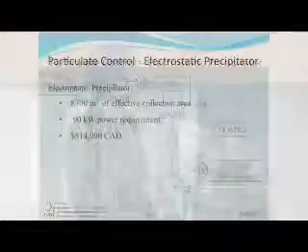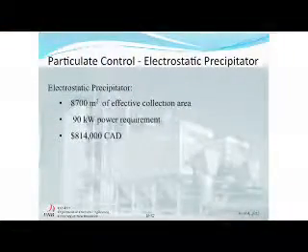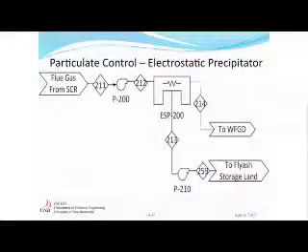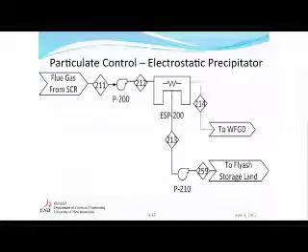So the flue gas from the SCR reactor will flow to the electrostatic precipitator to remove the ash particles. The removed ash will be stored in the land to be sold to the cement and concrete production companies. And flue gas will flow to the wet flue gas desulfurization unit to remove the SO2 particles. As you can see the blower here, we use a blower to maintain the pressure in the pipelines to just enough to send the flue gas out of the stack.